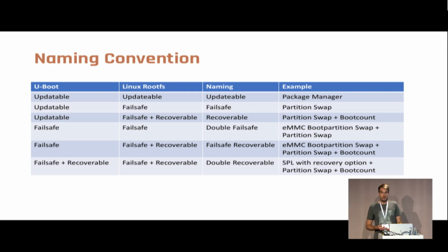Then fail-safe would mean that you can update your device in a way that if there is a power cut, it will continue to work. So if there is a power cut, it will reboot, and then it will just load the previous version of your software. That is fail-safe. And then furthermore, there is recoverable.